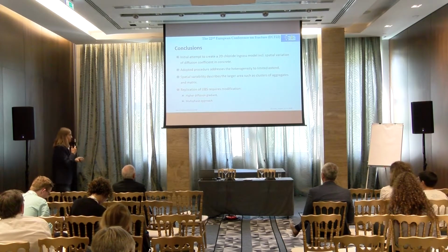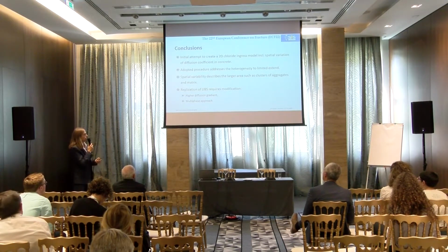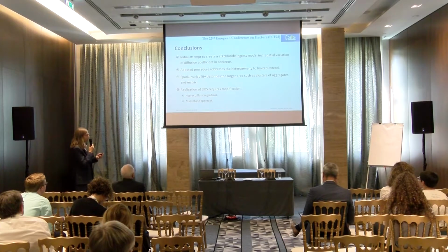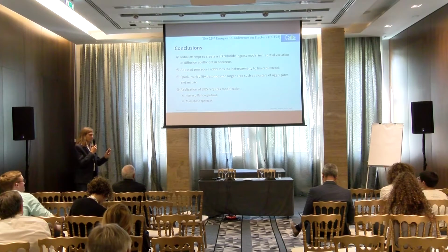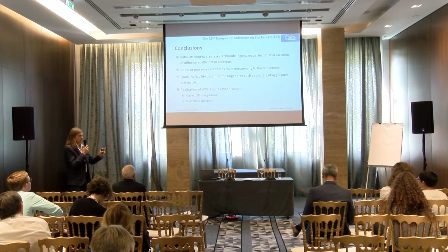And let me conclude. The initial attempt to prepare the 2D chloride ingress model considering spatial variation was presented. The heterogeneity was addressed to a limited extent, and it cannot address the aggregate and paste difference, the change of the properties over the aggregates, over the clusters of the aggregates and the paste.